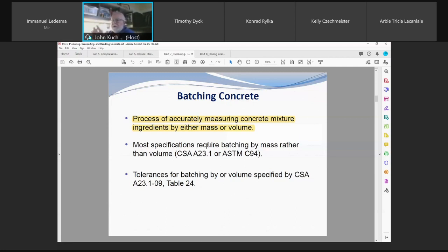So I determined how much a cubic foot of aggregate would weigh for my mix design. And I knew how many of those boxes I needed for, say, batching 0.5 cubic meter at a time, depending on the size of the job. So I dumped 0.5 cubic meter of aggregate into the loader bucket, leveled it off, and marked the inside with a felt marker to make sure that he always had the same amount. He would level it, and dump it into the mixer.